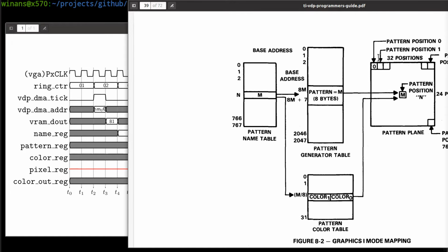All right, so we're going to see a counter that has to run modulo 16, based on which one of the VGA rows we're rendering right now. Okay? And each time we go over this set of tiles, this 16 times, we need to do the same tile numbers, the same name table lookups.